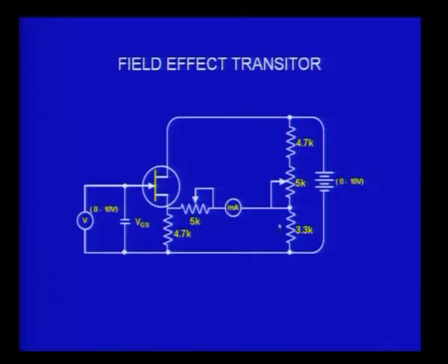So, this becomes a very convenient way of measuring an external voltage, because the input is reverse biased. I can apply a voltage here and correspondingly there will be a current variation here which can be measured by us, and therefore this becomes a very inexpensive FET voltmeter. You might remember an ideal voltmeter should have a very large input impedance.